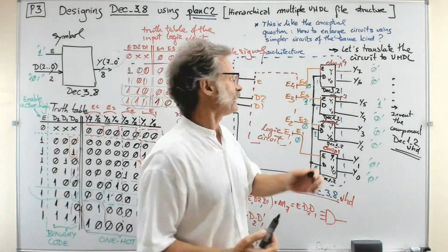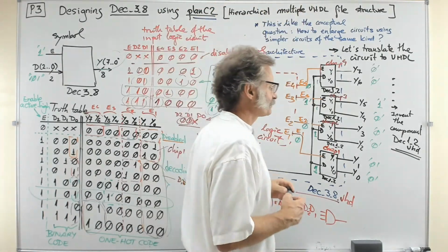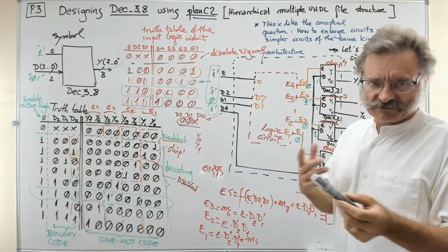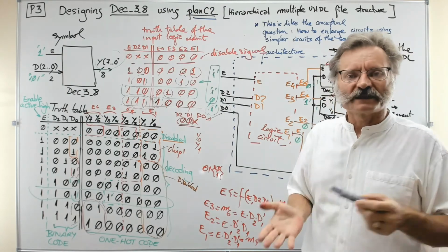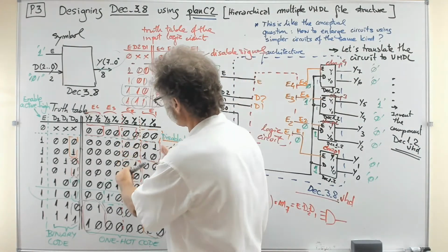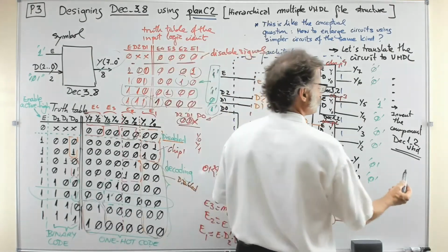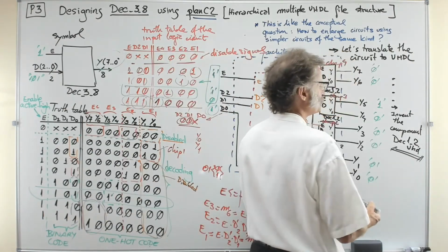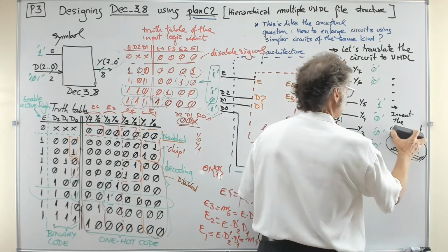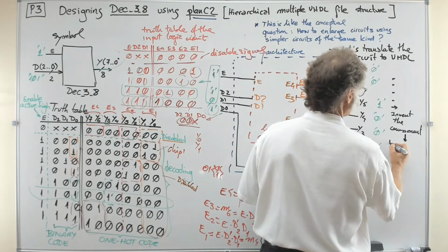Whatever the way, as a plan C2, it has no meaning at all, if you like, but you have to invent it. Whatever way, for example, using the plan B or the plan A, just take the simpler table belonging to a decoder 1 to 2 and just draw the equations. So this circuit is going to be quite simple, but you need it. You need the decoder12.vhd. You need that before proceeding.